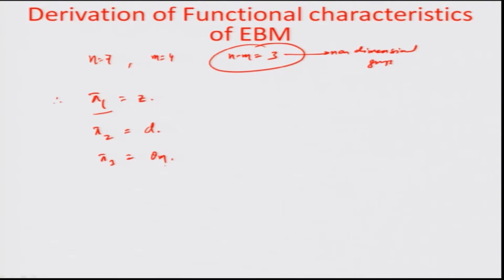So, apart from these 3 parameters, the other parameters which are involved in all the analysis are the power p, the velocity of the beam v, thermal conductivity k, and the volume specific heat capacity rho c. So, these are the basic 3 dimensions where there are linearization of the power of these with respect to the non-dimensional groups, and let us assume that we define coefficients alpha, beta and gamma, where the subscript changes between alpha 1, beta 1, gamma 1, alpha 2, beta 2 and gamma 2, and alpha 3, beta 3 and gamma 3 between the 3 non-dimensional groups here.